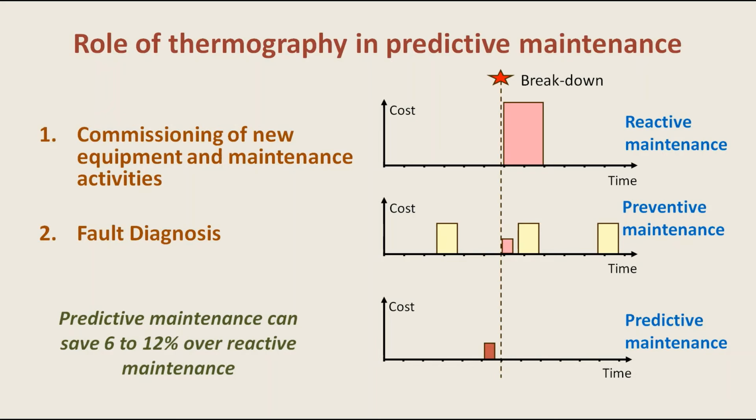So, corrective action can be taken before electrical equipment like electrical motors and circuit breakers are put into operation. In case electrical equipment demonstrates poor performance or is suspected of operating under faulty conditions, thermography helps to collect operational information so that corrective action is taken before the equipment fails to operate.